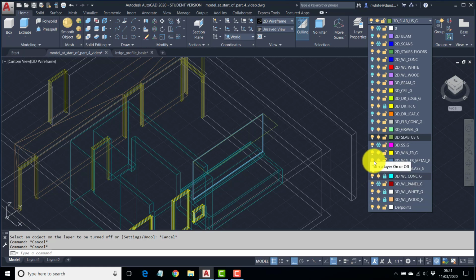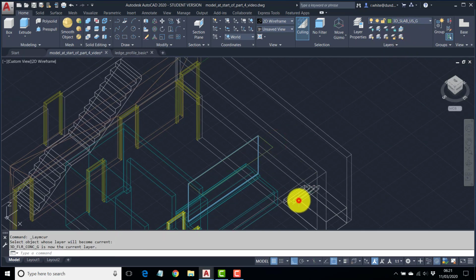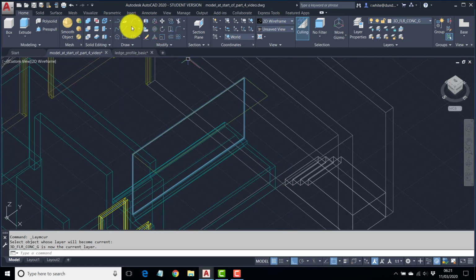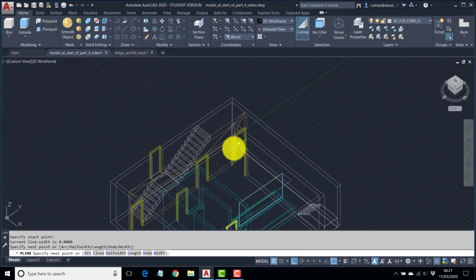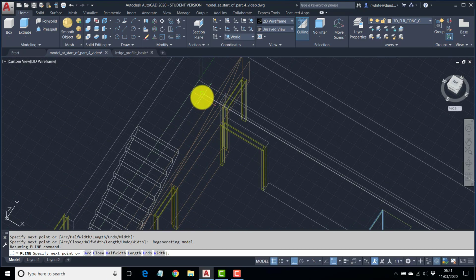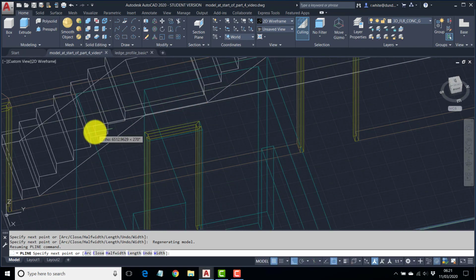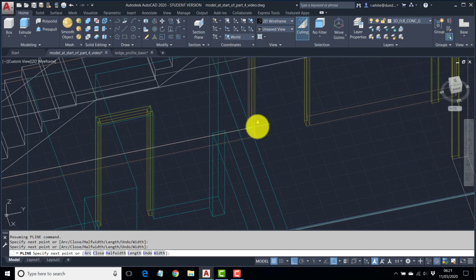So that was floors, concrete. So we need to see those. Okay, and make that your current layer. So we'll have kind of exposed concrete floors and then a wooden floor. So this is a wee bit tricky, drawing the shape here. So it's a polyline. I'm going to start at the corner of the stair. Okay, we'll go into the back area here, and we don't really need to go all the way to the bottom of the stairs, but actually we'll take it to this point, there will be a floor.